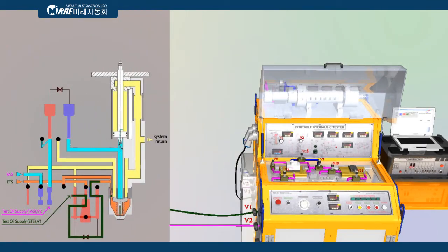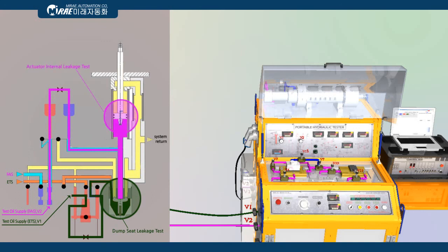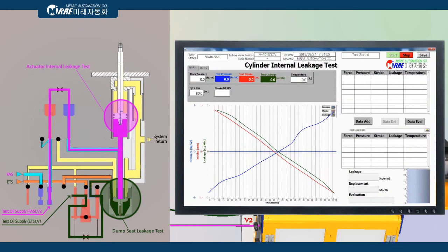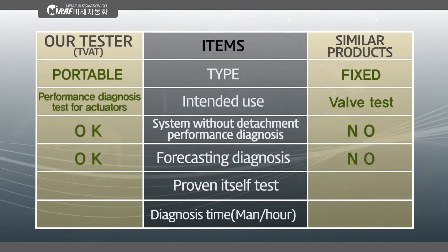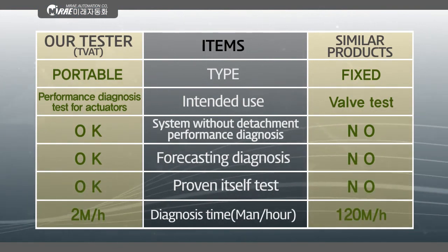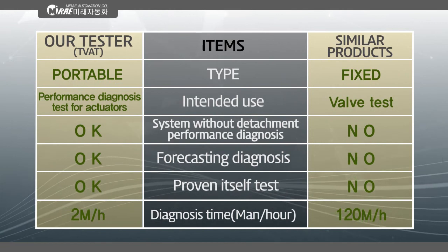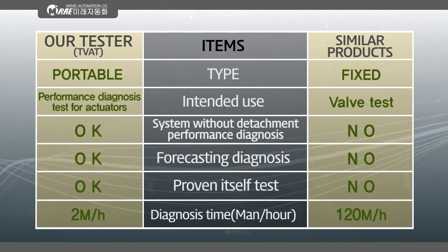Turbine valve actuator tester can improve the situation that turbine valve actuator must be detached from the hydraulic system and tested depending on outside service company. It can reduce the dependency of test, enhance the reliability of maintenance by the self-test of steadiness, and obtain the power stabilizing effect by preventing generation reduction and enhancing the operation rates. The key differences are: the conventional method cannot test the performance diagnosis of turbine valve actuator without detaching the actuator from the hydraulic system, and it is impossible overall check of turbine valve hydraulic actuators in permitted work time.